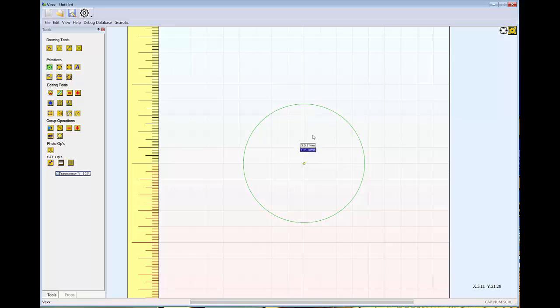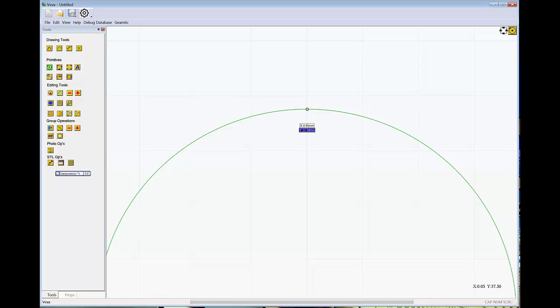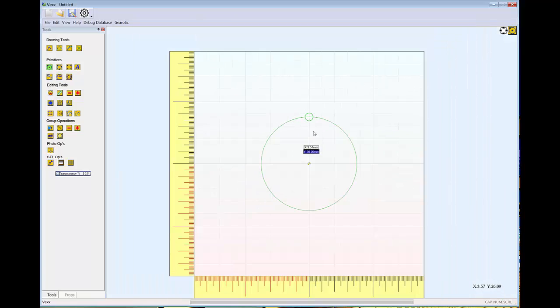Now each of the iris leaves that are in here, we want them to have a swivel to swivel on. So we're going to use the same 2-point circle, and right up here at the intersection of the circle and the center line, I'm going to enter a 0 in the X, and then I can just click on the circle, and now I can create a circle of 6.25 millimeters, 1/4 inch, so that I can use a 1/4 inch swivel.